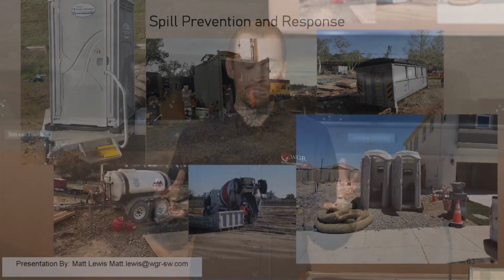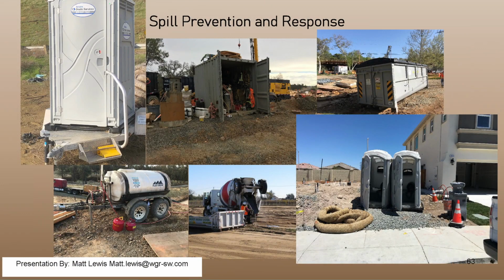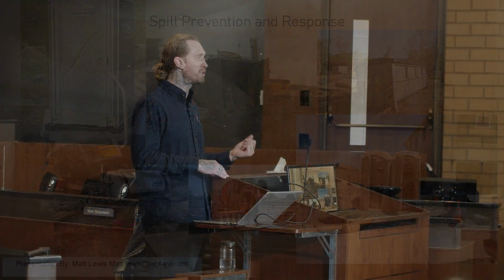usually the superintendent. And it generally is no more than a bucket, a shovel, some cat litter, maybe some absorbent materials. What a state inspector will always say is, where's your spill kit and where is your spill personnel? Where's your spill team? That's why I usually train the superintendent, because they're probably always going to be on site versus just a general laborer.